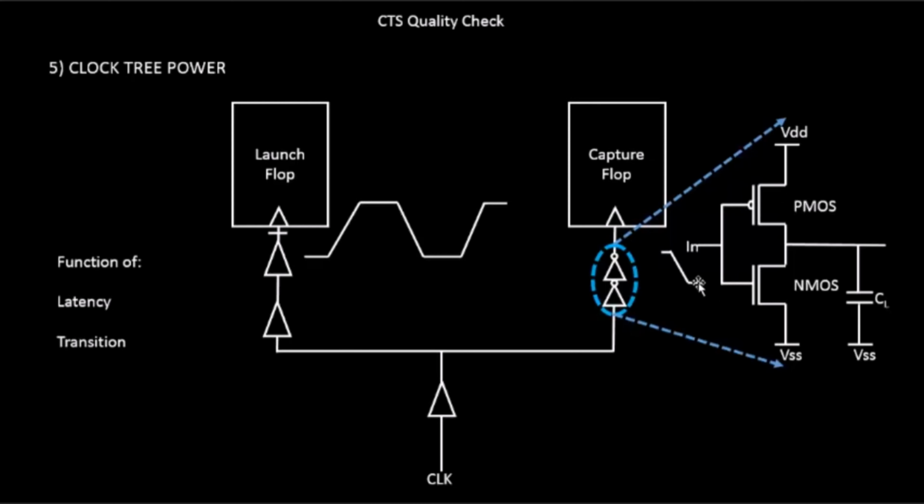So let's look into this particular scenario where your input is at logic 0. Basically it is switching from logic 1 to logic 0, and when it reaches over here, it is at a stable condition. So you have a 0 over here. When you have a 0 over here, your PMOS is on, your NMOS is off. Let us try to draw that. A zero is nothing but a VSS. So you have the PMOS, the gate of the PMOS is grounded to VSS, and the NMOS we have removed because in this scenario your NMOS is off.